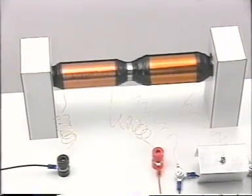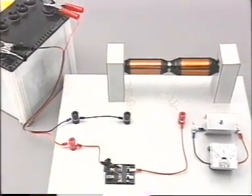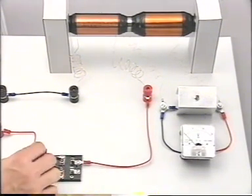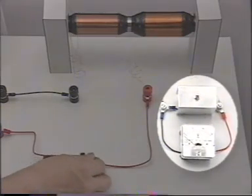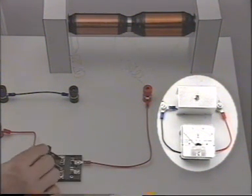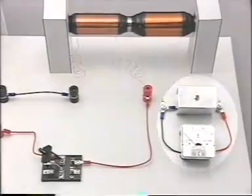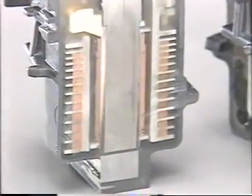Next, let's do another experiment. Two coils with different thicknesses of wire and numbers of windings are connected in series. The moment the switch is turned off, the flow of current in the primary coil is cut, generating a greater current in the secondary coil. When the current is switched on and off in the primary coil, a high voltage is generated in the secondary coil. This is called the mutual induction effect. An ignition coil integrates these two coils into one.